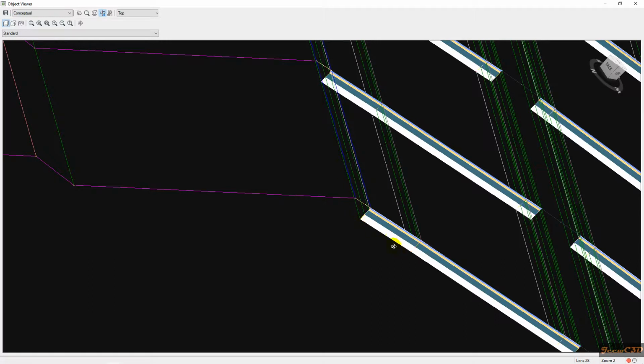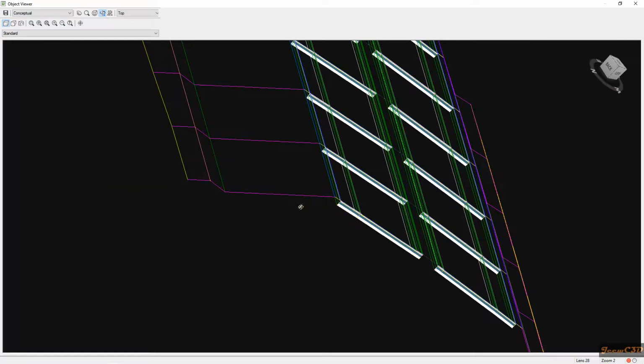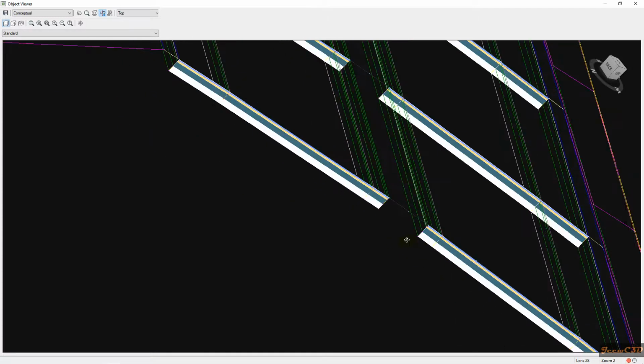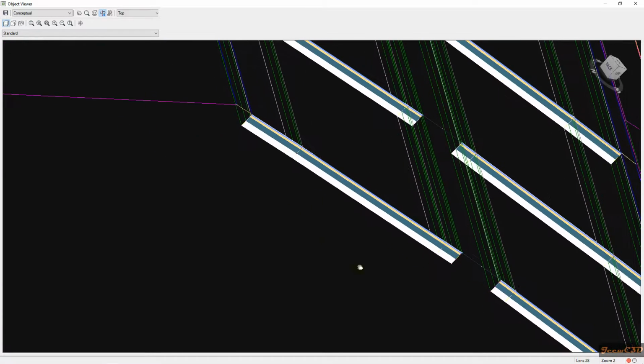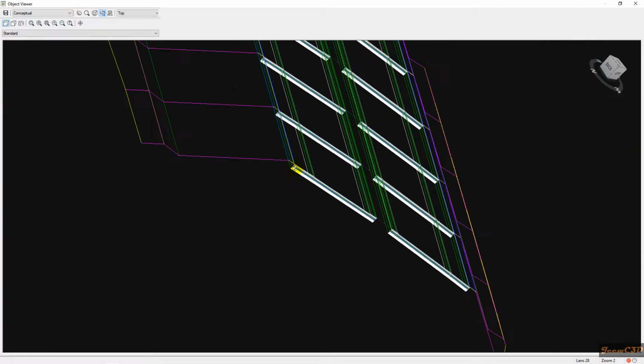It will connect all these bottom lines and it will make a surface from these bottom lines. You can see there are connecting lines. They are called feature lines. All those feature lines will connect as a surface when we are creating a datum surface. Now we will look at how to create that one.